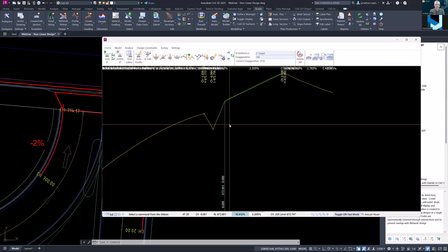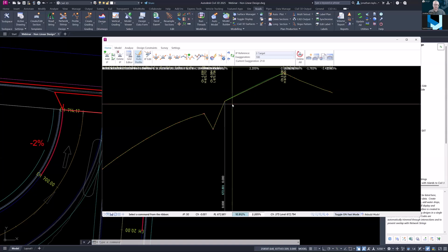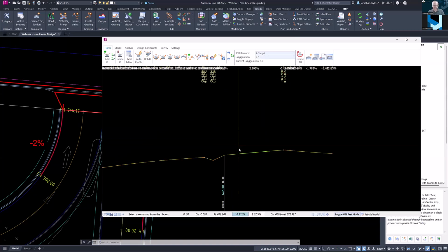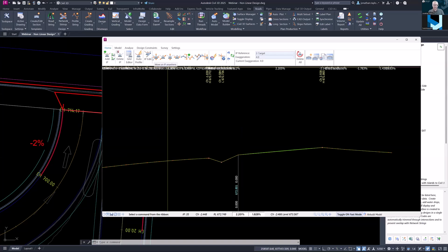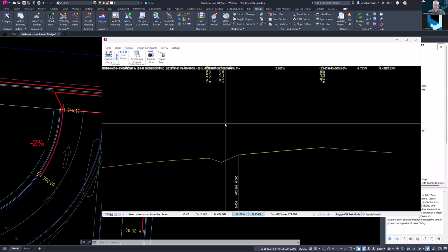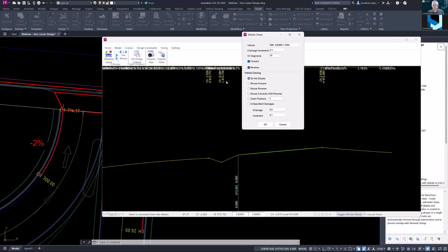There you go. So what I'm actually seeing here, if I run the analysis, I'll actually be tracking over my design. Reduce the vertical exaggeration. Thank you, Todd. Yes, I thought that might be it. There we go. Doesn't look quite as bad. Yeah, it looks more realistic. It does now. Looks like you could actually drive over it rather than have to use crampons. So you could even extrapolate that concept if you'd done a model all the way through to, say, the back of a footpath near a property line. You could make that your matching point.